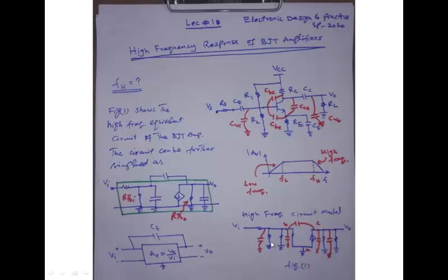You can see that these three resistors are in parallel. So we can solve them in parallel and convert them into one resistance, which is R Thevenin I. R Thevenin I is nothing but the parallel combination of these three resistors, and R Thevenin naught is the parallel combination of these two resistors.